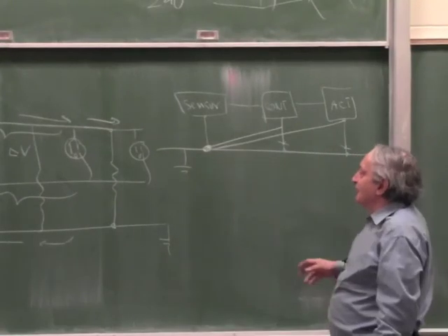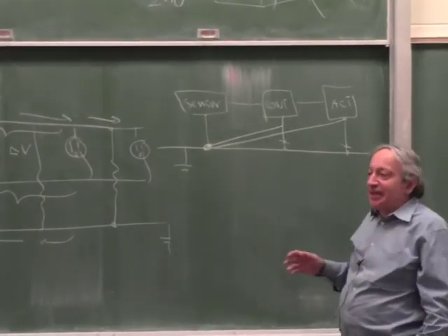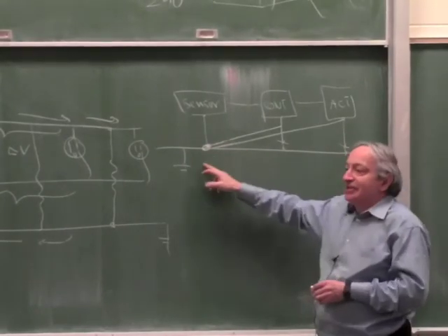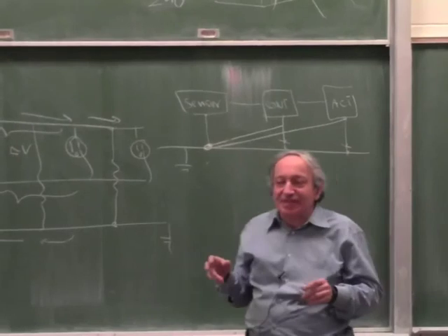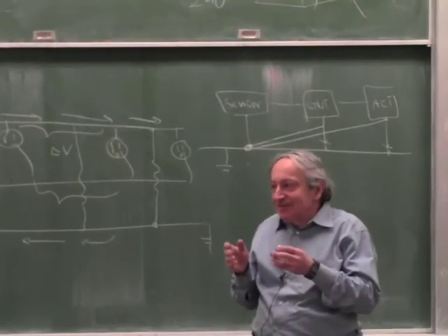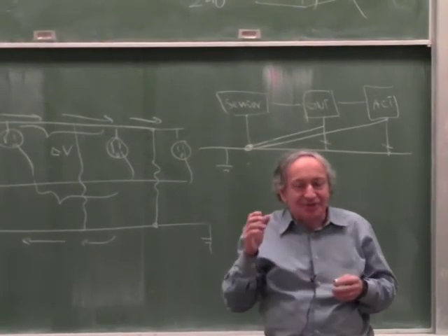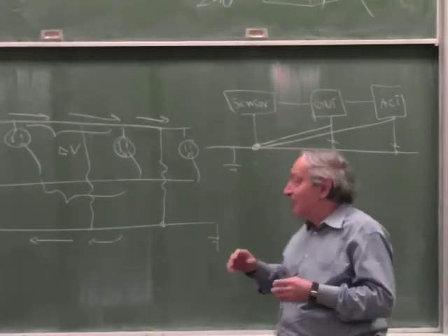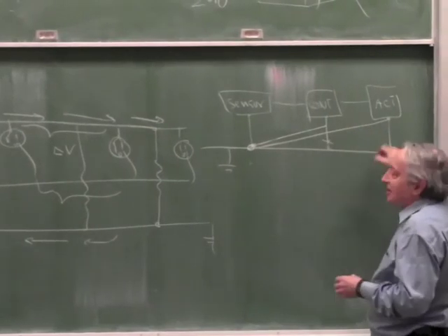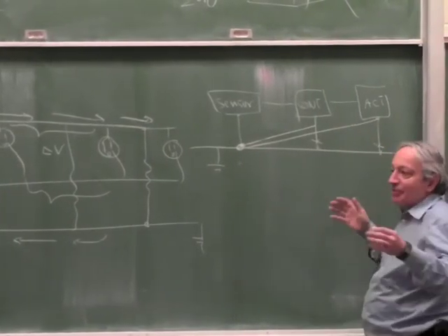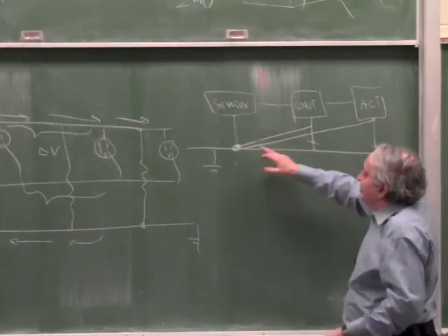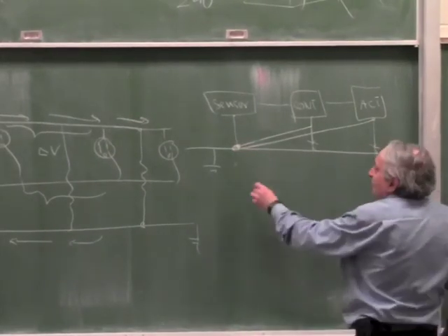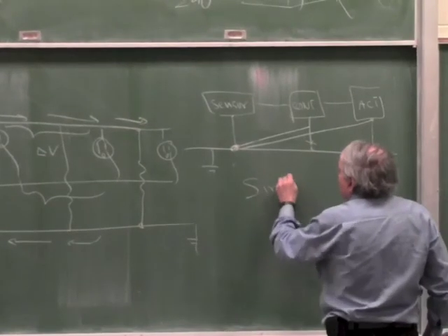Sometimes it's also referred to as audio style ground, because in audio amplifiers the parts inside are grounded this way. An audio system is very sensitive to picking up hum, because you can hear the 60 hertz. It's audible. This can happen if you have multiple grounds inside the audio system. So if you have a big audio amplifier, they bring everything to one point. So that's single point grounding, or central point grounding.